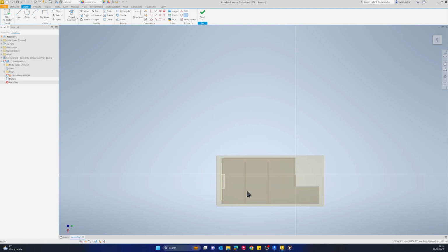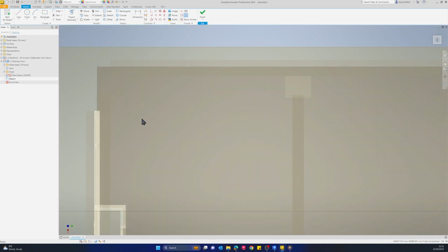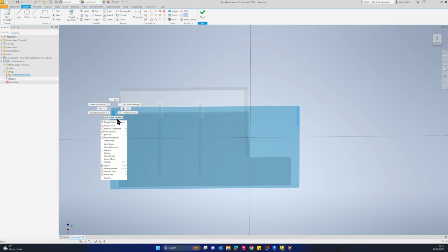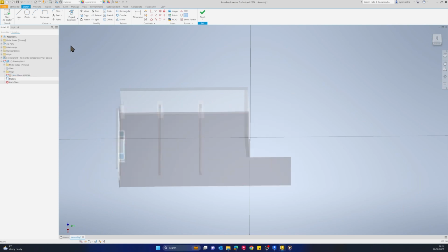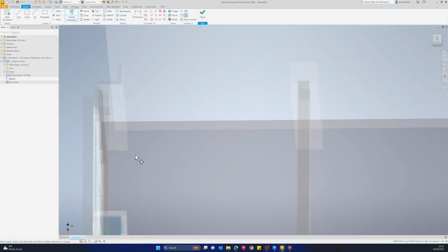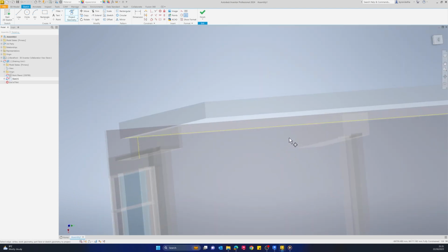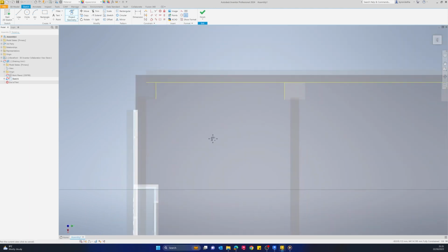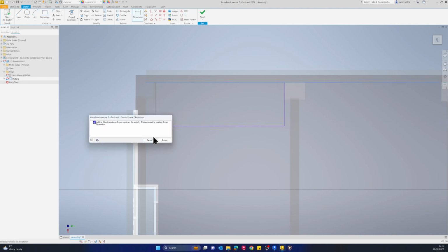And we can draw some very basic shelves using the original geometry. So I'll just use my project geometry tool. I'm actually going to turn this off if I can, just so that I can have access to those walls. And then I'll just project the pillars and the back face of the wall that we can use as our reference to draw our shelving units.